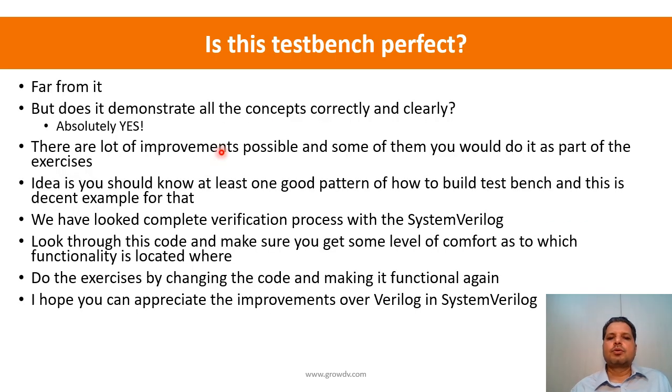So this concludes, right? We have successfully built a FIFO test bench using SystemVerilog, and we went through the planning phase, we went through the development phase, and we briefly looked at what happens in the regression phase: how we compile, how we run tests, how we run multiple tests, how we can merge those databases, and when a test fails, how we go about debugging it, right? So briefly, we got an overview of each of these phases.